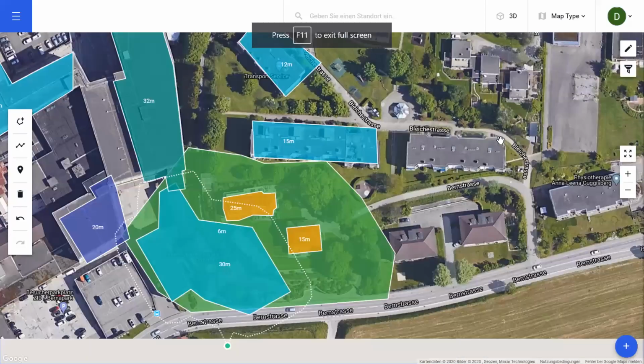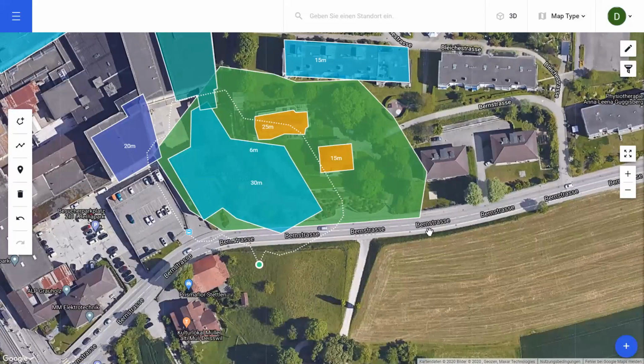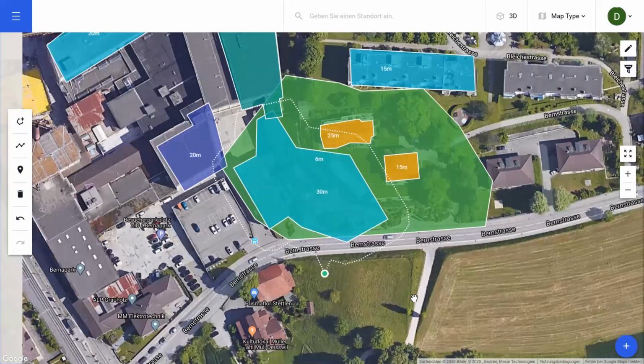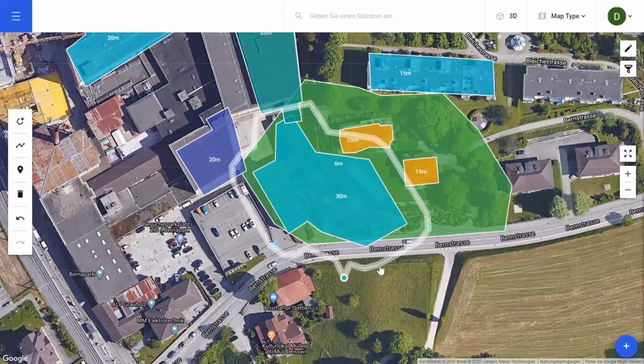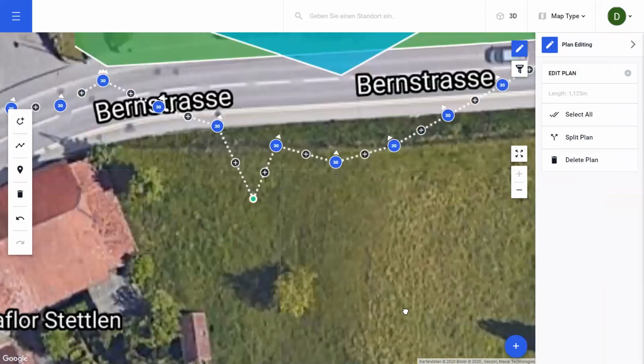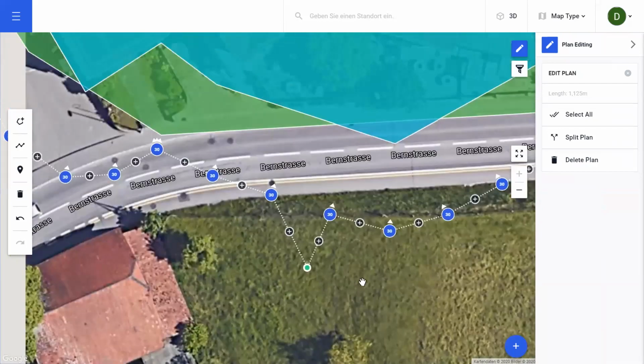And we will look at, for example, one of our top-down flights, or perhaps even at this perimeter vertical mission that we have created. So let's click on that mission. And you see that as soon as I click on a mission, I start getting all of the waypoint information about that mission.